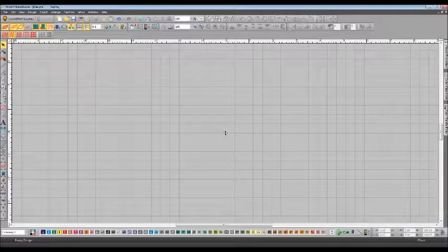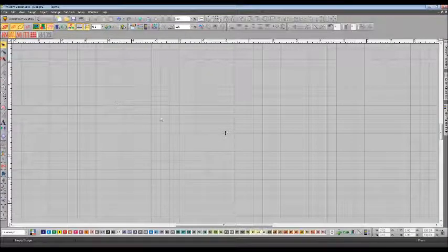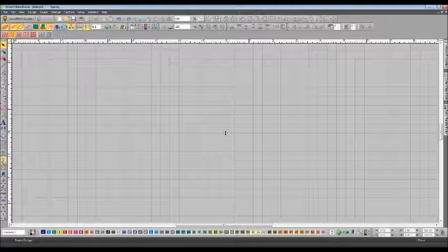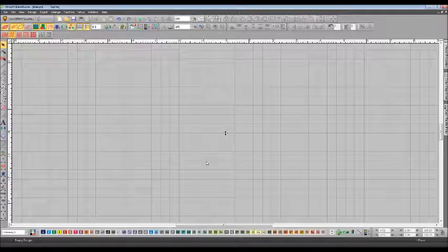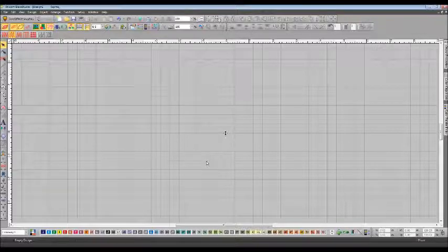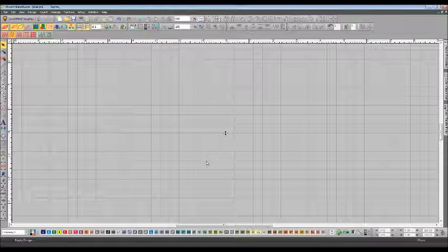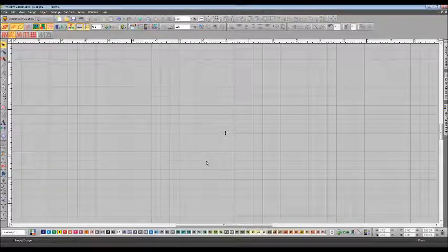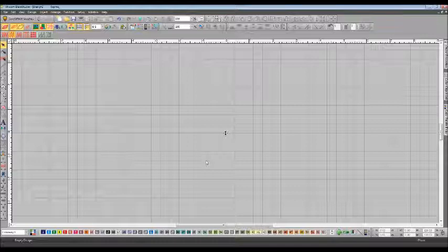Now the reason why I have that one open is because there's always going to be a point in time when I'm digitizing where I have to go back through by object or back through by function and make sure I'm doing things the way I see it in my head. Because there are times, and now I'm talking hand digitizing, not automatic digitizing, where the machine will add a trim where I don't want to trim. So I need to travel back through functions or through trims to delete that stuff.